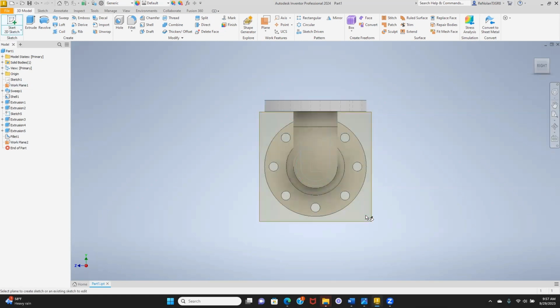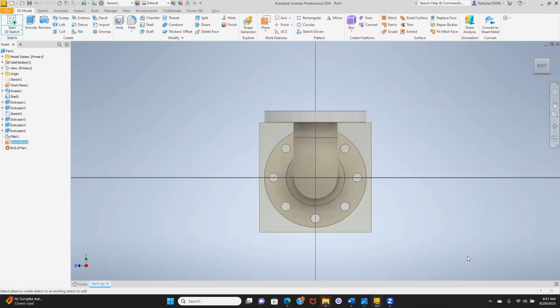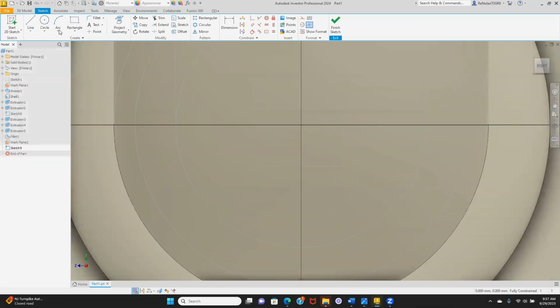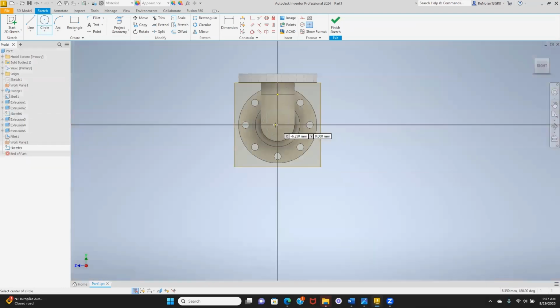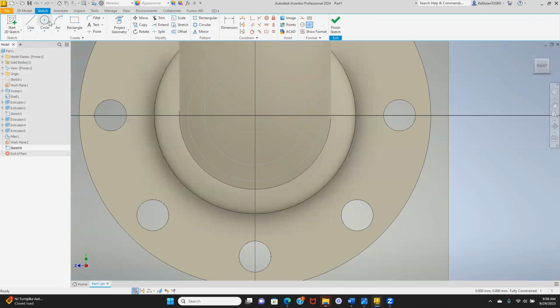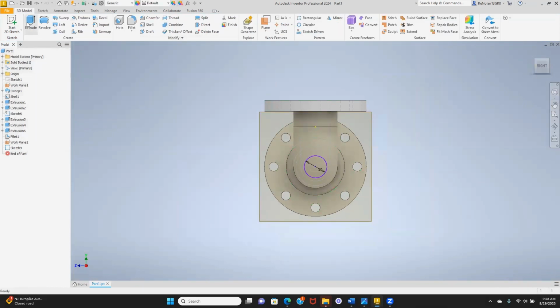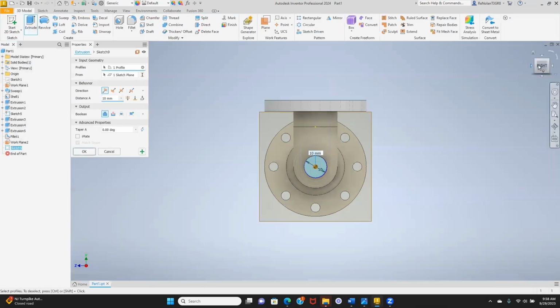Let's create a sketch on our new plane. We're going to focus in on that origin point. Again, this plane is centering on the same point as the center of the circle we're basing it off of, or the face we're basing it off of. So let's create a circle with a center at the origin here with our 50 diameter as per our drawing.